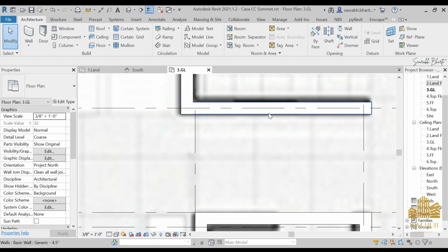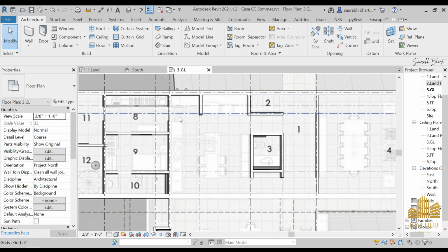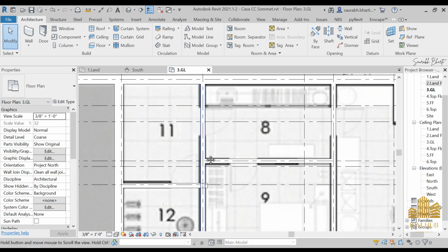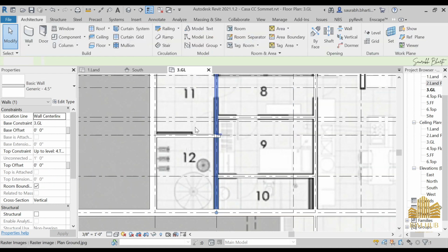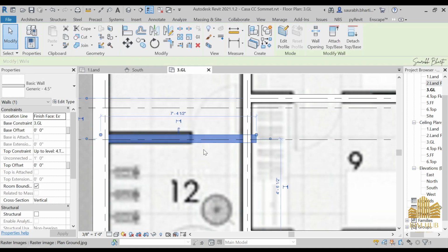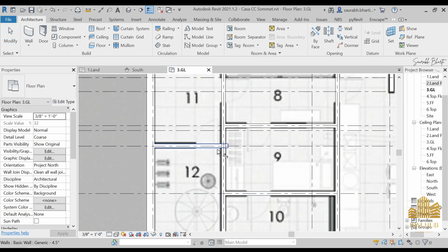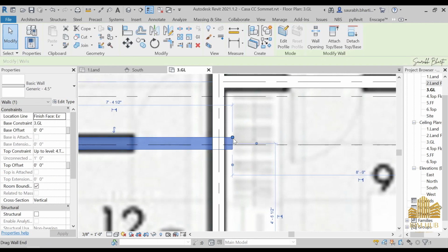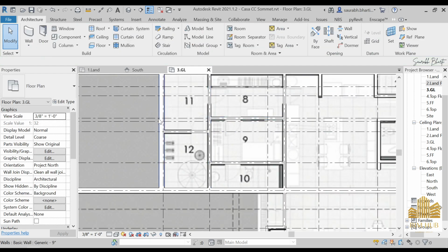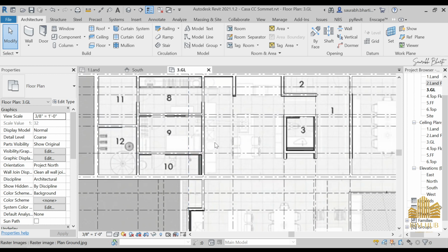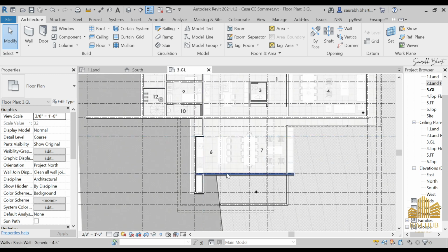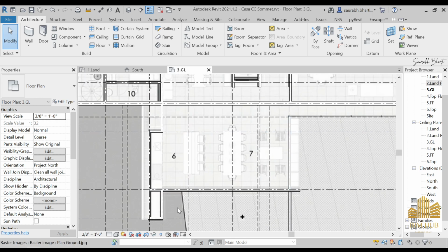Yes, then you can make these changes wherever you want to. So I'm just selecting this, and yes, done. Select this one, make a little bit of changes to this wall. Again, just trim. Okay, not just trim it out, actually you can just make it smaller from this place, and now it is just placed as one wall. So wherever you can see the gap over here, that black bar ends over here, there is our door. So remember that we have to make the doors over there. And now I think we are done with the outer part of this building.